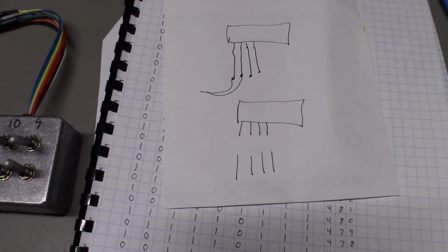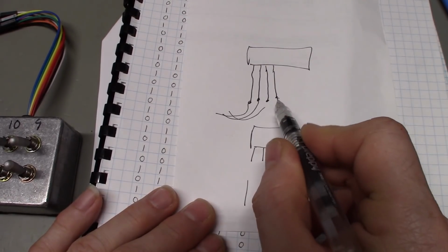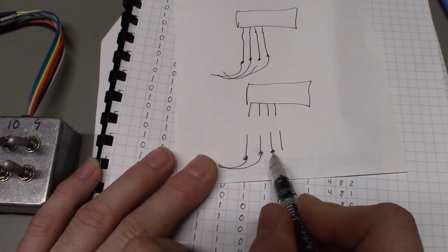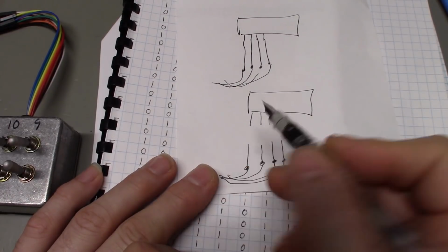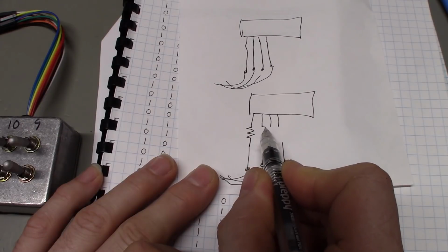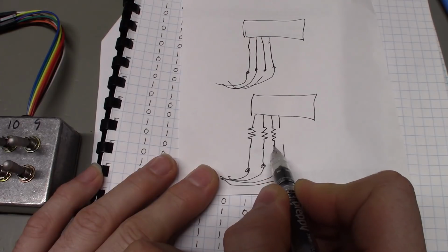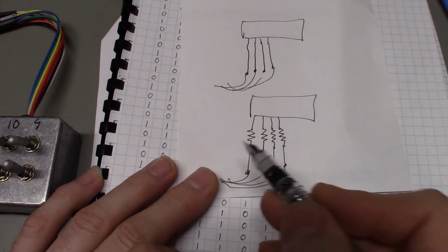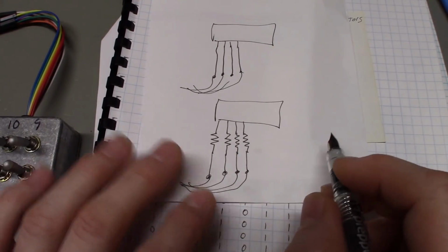Okay, and that's going to still be the same. On this side, you would still have the wires going off to the channel selector switch, but you've now cut the traces. And what you're doing is adding a 3.3K resistor in series here, basically. That's it. That's all I did. Those traces were cut, I bridged them with a 3.3K resistor, and now what you would have is your toggle switch.